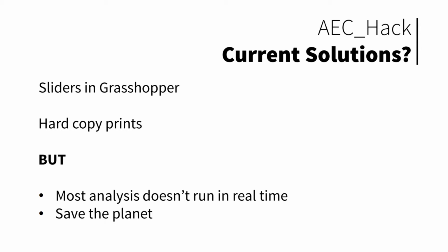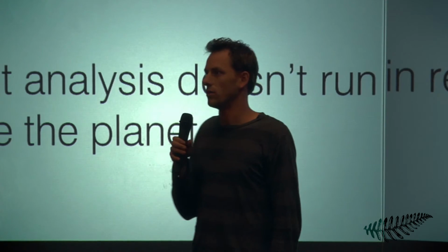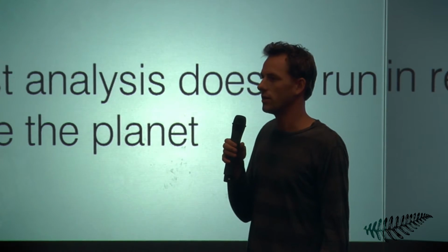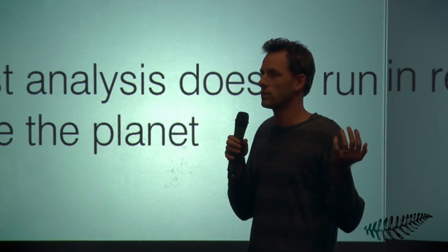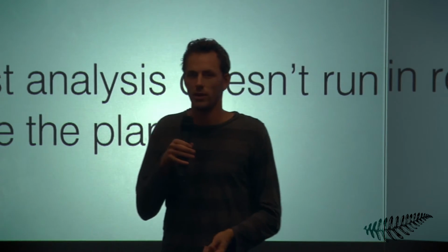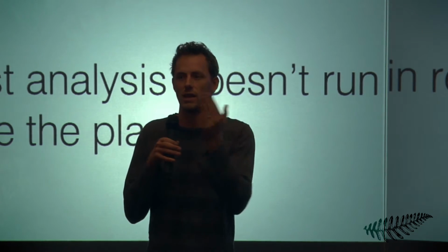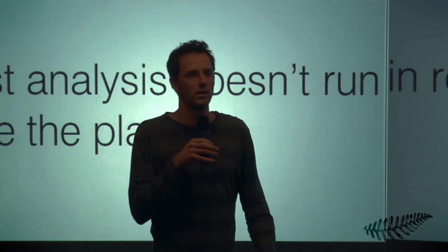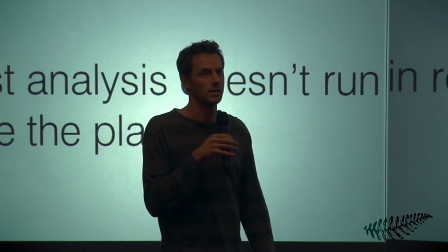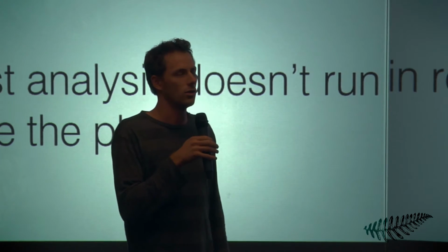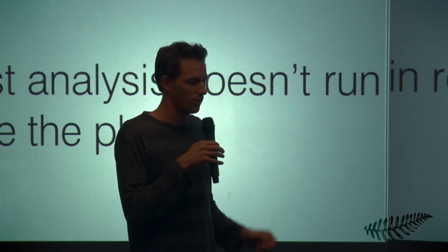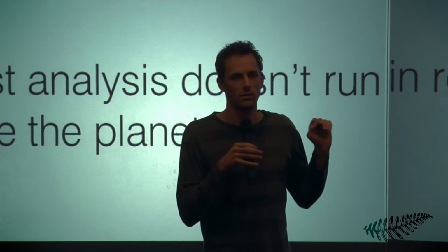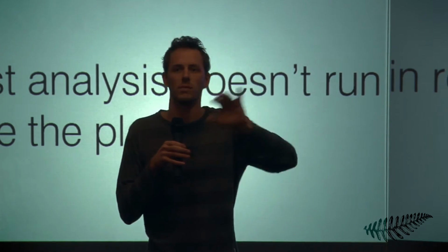So as I said before, you can use Grasshopper in some respect to use a slider and scrub through different solutions. But of course, not all analysis that you run for buildings, like daylighting analysis or thermal analysis, runs instantaneously like that, so you can actually scrub through it. A lot of it takes a lot of time, maybe even hours to run. And so the idea here is to create a platform on the web in which you can display your pre-baked analysis runs.